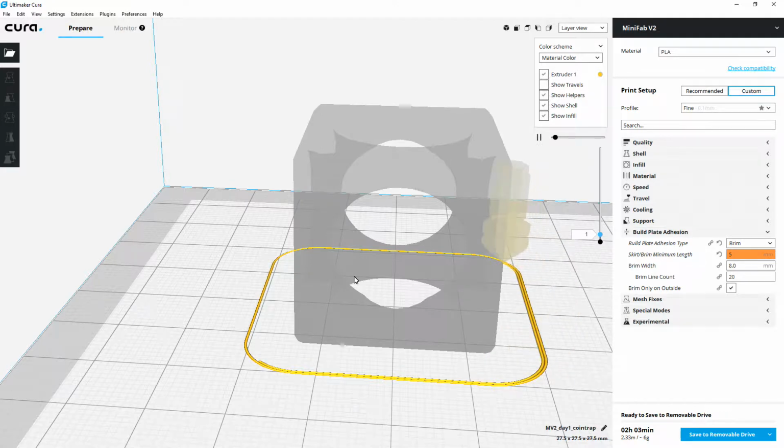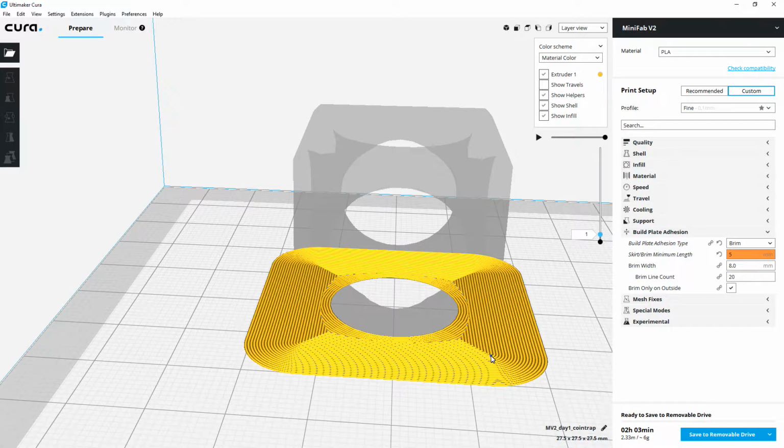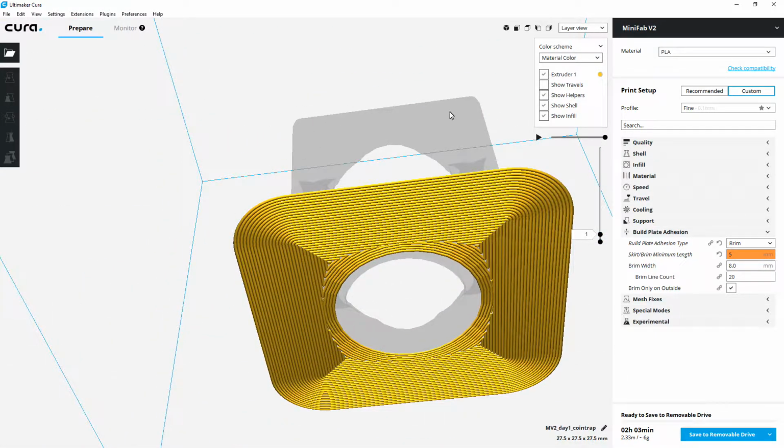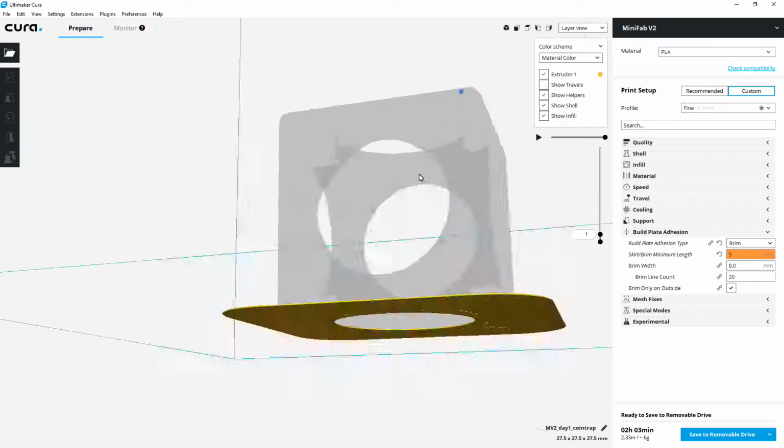This is good because this little thin layer down here on the bottom peels off pretty easily. You just grab it with your fingers and peel it right along this edge, and it comes off. Occasionally there might be a little part you have to cut off or sand off, but this comes off surprisingly easily, and it makes a huge footprint, as you can see from the bottom. It takes the entire thing. Huge footprint. Might be overkill. Be careful, because sometimes if the footprint's too big, it can be too difficult to remove the part from the print bed, and you end up yanking on it enough that you have to re-level the bed.